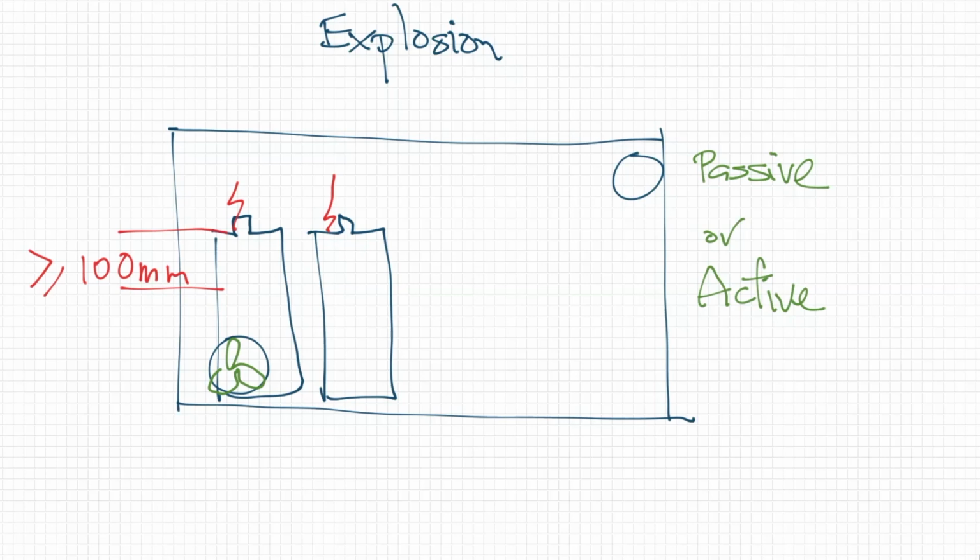Okay, and there's just one more clarification requested for large battery systems. Even if it's good practice not to install a battery system with an arc greater than 4 calories per square centimetre in a residential site, legally speaking it is not forbidden, because there is not any standard that officially covers the installation of such a system.